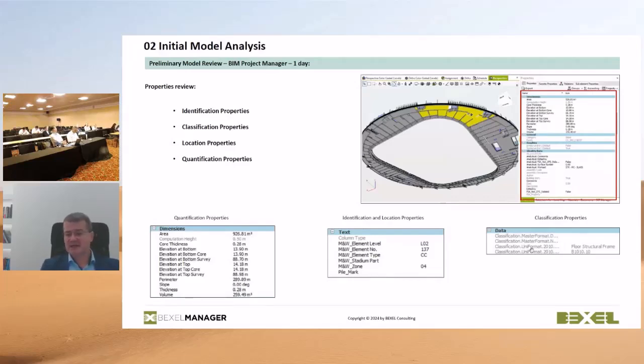The second thing was with the automated data enrichment ability to add various classifications. So just to give you an idea, the system recognizes if the element is, let's say, IFC slab, and the property is it bearing is true. It will, if we are using uniform classification, automatically generate two additional properties, in this case B1010.10 and floor structural frame.